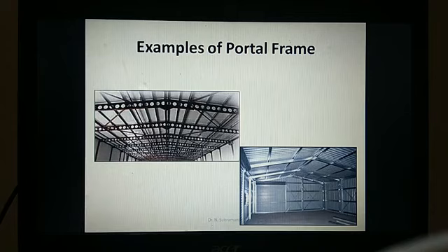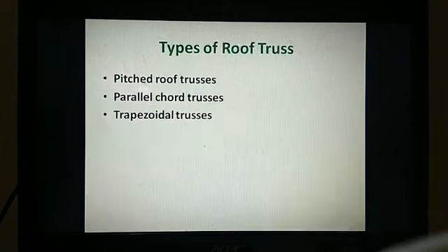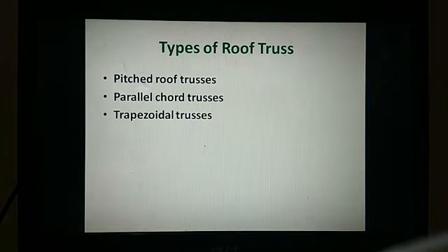So when you are going with a pre-engineered building, the section will be completely a solid I section, a solid built up section. When it is a solid built up section, the structure self weight will become more. To reduce the self weight of the structure, you can go with something like castellated beams like this, where you can avoid section weight. Okay, this is how castellated chords can be provided in PEB structures, where the structure is going to be economical in terms of its design. Okay. So what are the different types of roof trusses available?